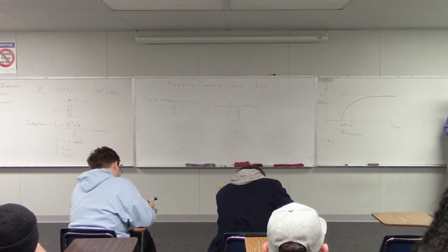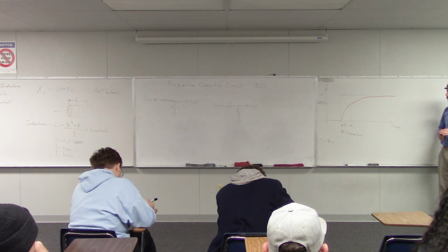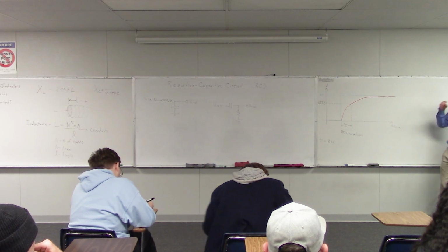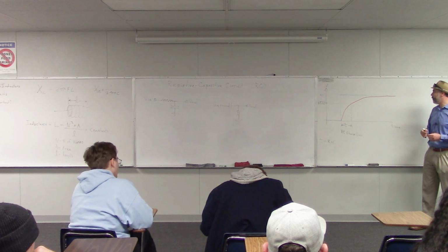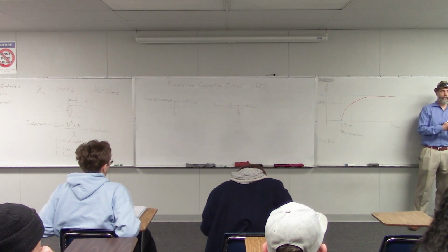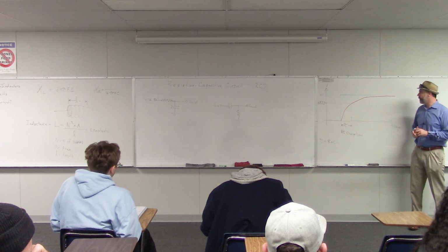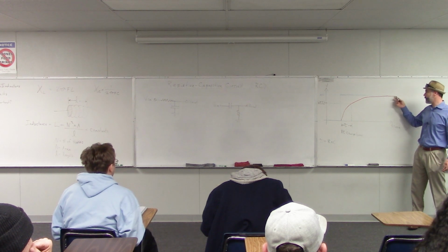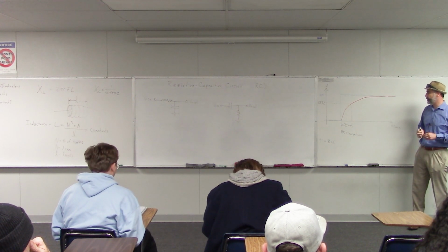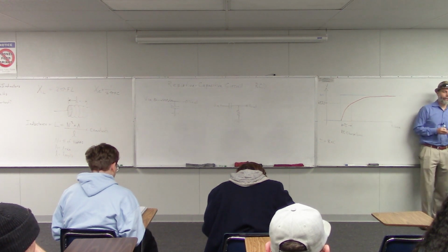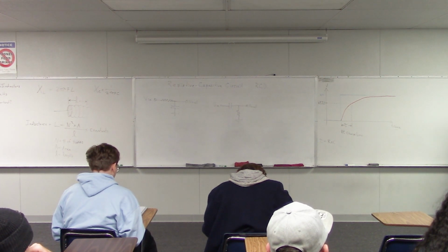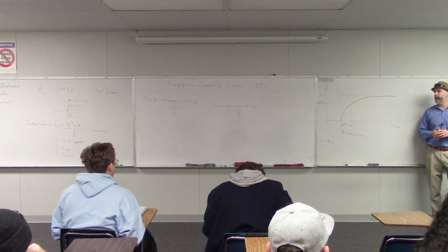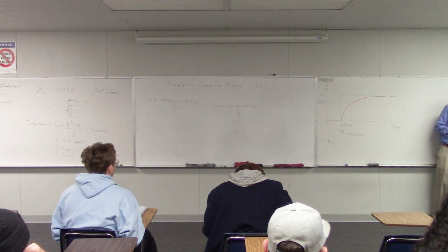Now, what if we want to know how long it takes to fully charge this capacitor? Well, I already said, theoretically, it would take an infinite amount of time. It'll take forever. But in practice, you can see that after a while, the capacitor value gets pretty close to the input voltage. So it'd be nice to know how long it takes until that capacitor is close enough to the input that we call it good enough, and we say that's fully charged.